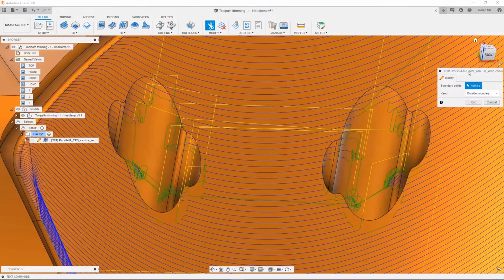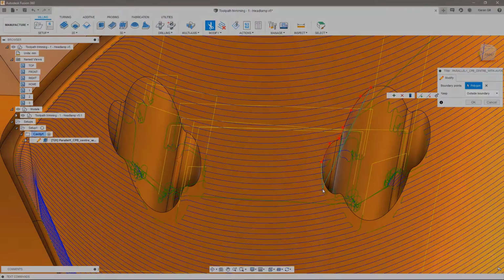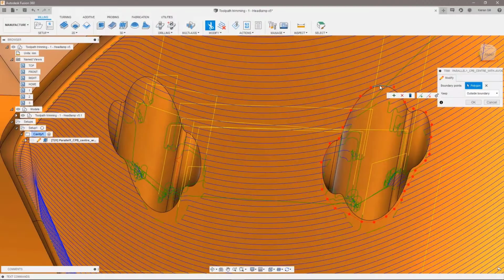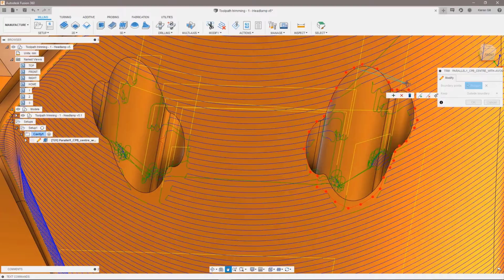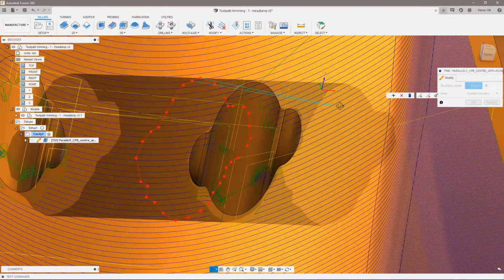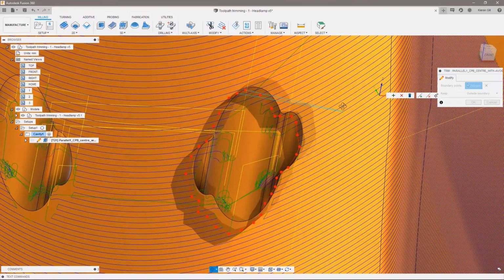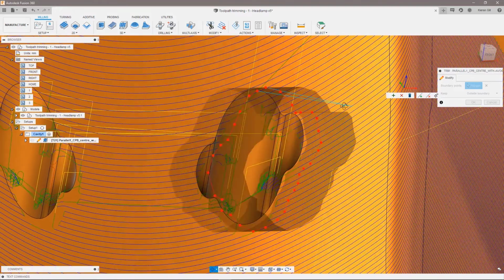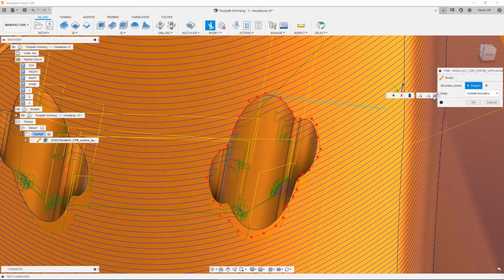By clicking on the toolpath editing icon, we can then start to sketch around the toolpath segment that we wish to remove from the toolpath. The sketching of the polygon is created in 2D and is aligned to the view at the point of clicking the toolpath editing button. If you rotate the screen to get a better view of the area that you are sketching, you can easily navigate back to that view by clicking the Restore View button on the editing dialog.